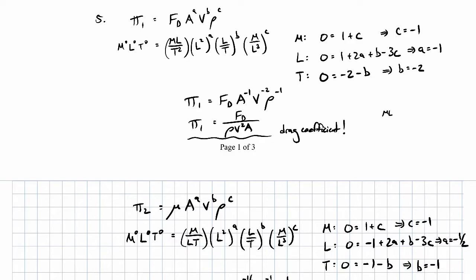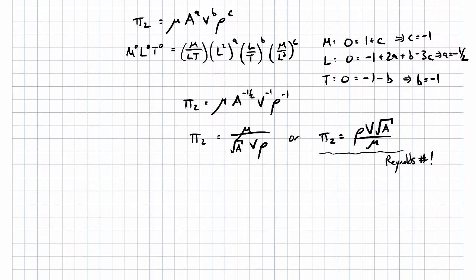So the drag force units or dimensions are mass length over time squared. Then we divide through by density, so that would be like length cubed over mass. Divide through by the velocity squared, so that'd be time squared over length squared, and then divide through by the area, so that's 1 over length squared. See, the masses cancel out, time squareds cancel out, length to the 4th in the numerator and length to the 4th in the denominator, so that's all okay.